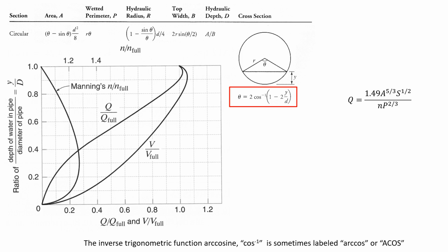So if it's mostly full, you've got a huge cross-sectional area compared to not that much of a different wetted perimeter. I mean, the wetted perimeter of this one's probably double, but the flow area is probably 6 or 7 times as great. So as a result of that, we have to correct for the n value if the pipe isn't full. And so that's part of what is being illustrated in this nomograph.